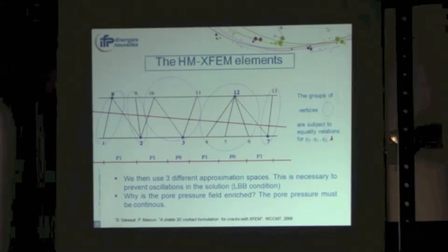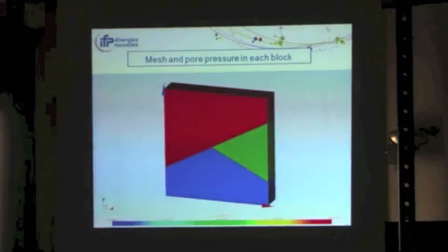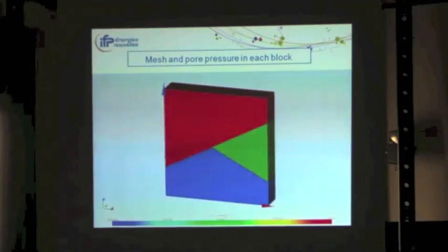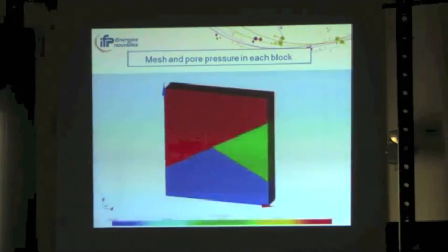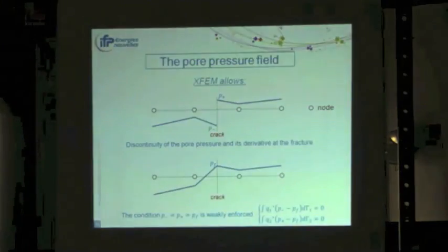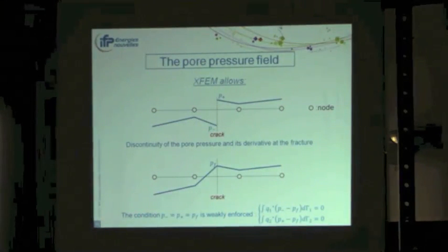So now just a last point, why is the pore pressure field enriched? Well, this allows the pore pressure to be completely discontinuous over the fracture. So here is a constant pore pressure in each block. So this is what XFEM allows.